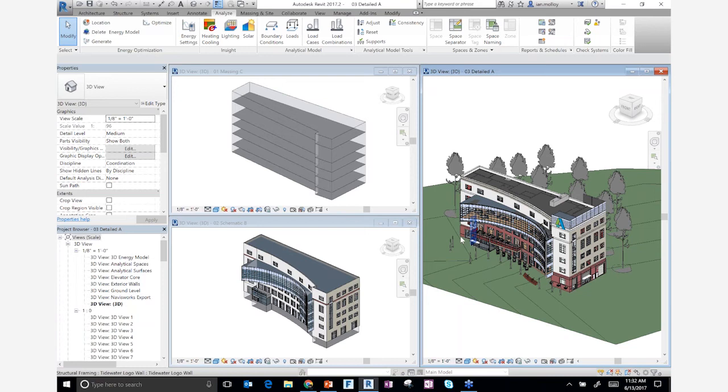I would also always recommend, don't necessarily start with your biggest, baddest, detailed design stage Revit model. The learning curve is going to be longer on that the first time. Start with something smaller and simpler, and you'll get to understand the way the energy model is created and what you're looking at. And then there's essentially one of three workflows you can follow, all of which are detailed online, depending on what stage in the process you're at, and what your real target is and how much time you have.